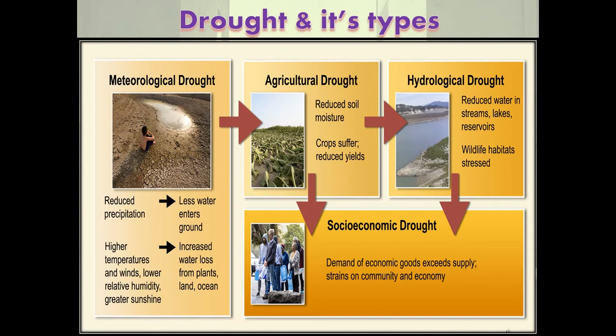Now, hydrological drought. It is brought about when the water reserves available in sources such as aquifers, lakes, reservoirs, and rivers fall below the statistical averages. It is associated with the effects of periods of precipitation shortfall on surface and subsurface water supply, rather than with precipitation shortfalls themselves. Hydrological droughts usually are noticed sometime after the occurrence of meteorological and agricultural drought, because more time elapses before precipitation deficiencies are detected in reservoirs, groundwater, and other components of hydrological systems. As a result, impacts of hydrological drought are out of phase with impacts of other drought types.